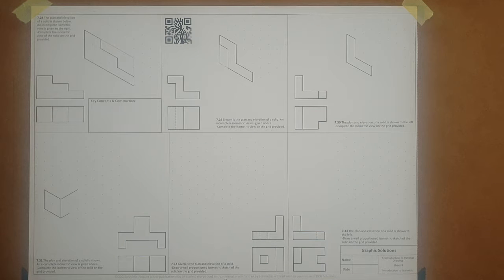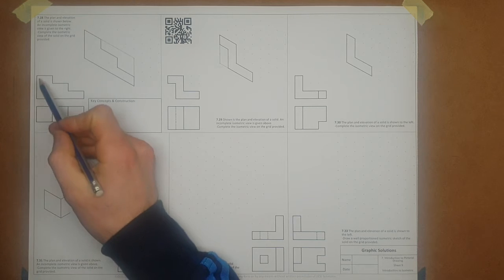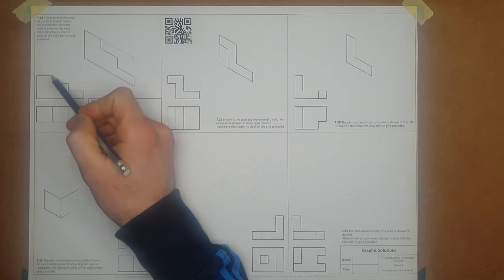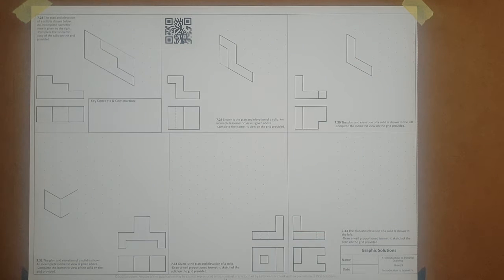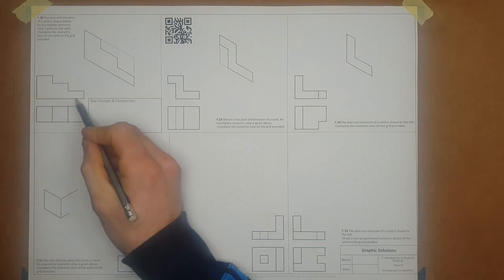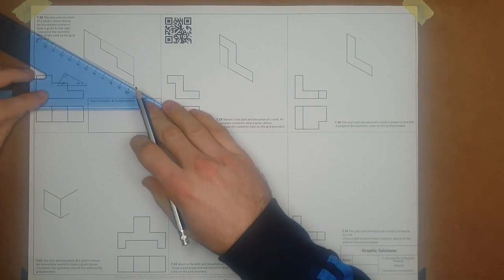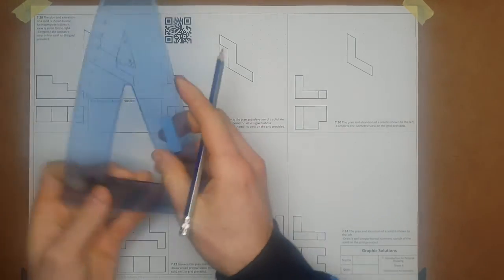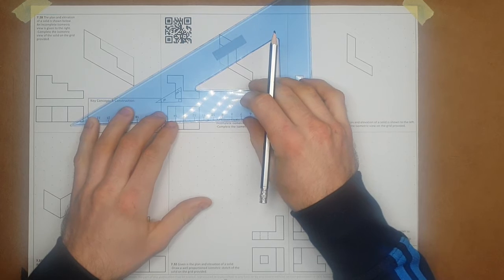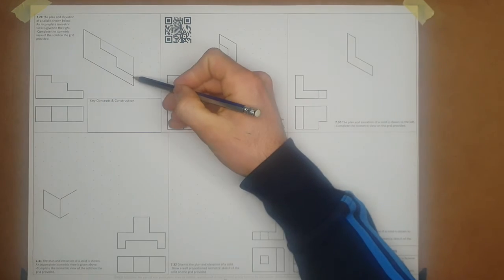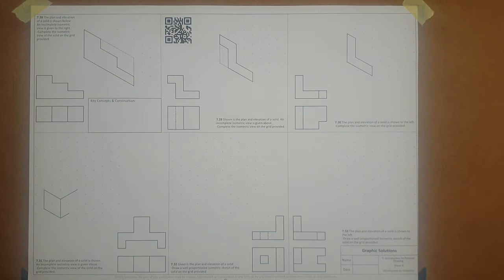The difference between this and oblique: in oblique projection, for flat, basic objects, you usually draw the full elevation first, and then you go off at 45 degrees. In isometric, there are no horizontal lines, so what was horizontal is now 30 degrees. Everything is going to go 30 degrees to the left, or 30 degrees to the right. But similar to oblique, vertical lines will still remain vertical.